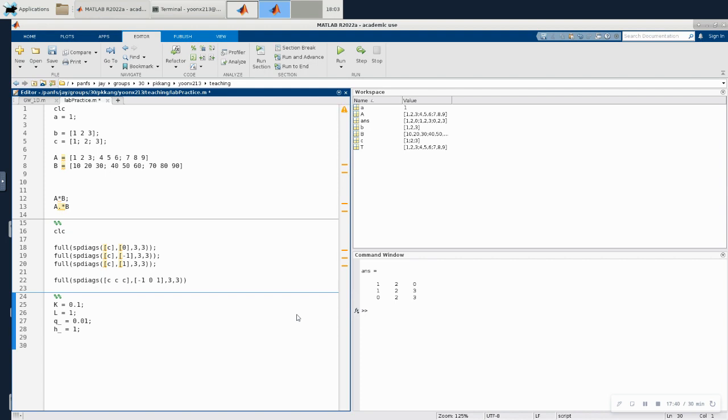And now let's discretize the one-dimensional groundwater system. First, let's declare an n variable, which is the number of grid cells within the system. I will use the value 5, which means I will discretize the one-dimensional system into 5 segments. Then the cell size will be estimated as L divided by 5, right?